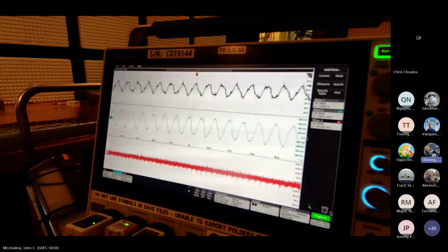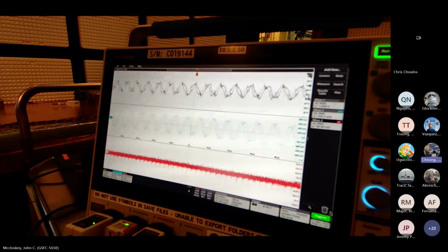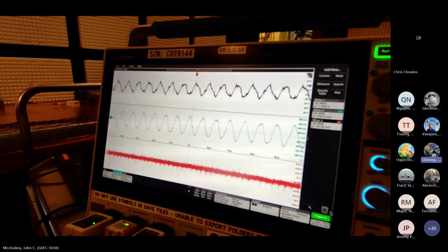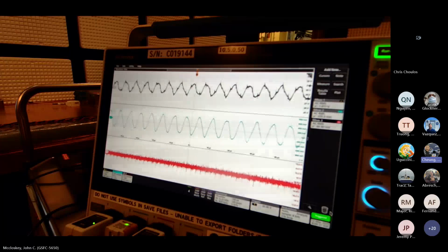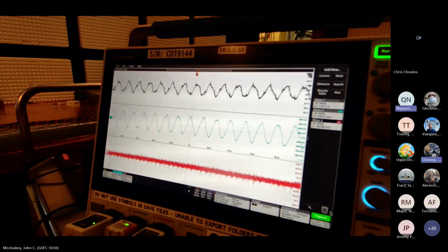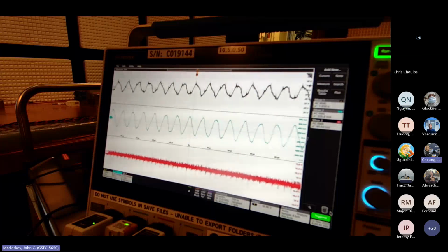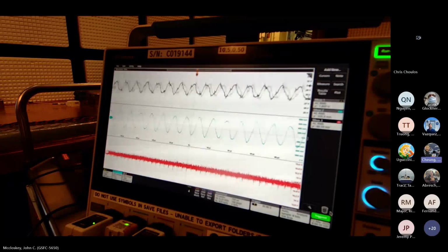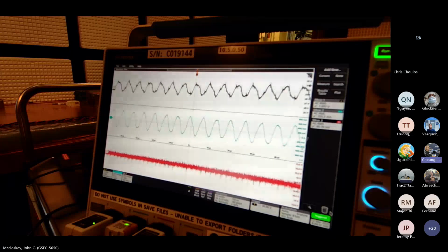Yeah, I'm comparing that to the feed through of the 30 hertz, which was 160 millivolts. So it seems like that's smaller than this peak to peak. Well, I guess that's about as good as this converter is in that couple of hundred millivolt peak to peak range.